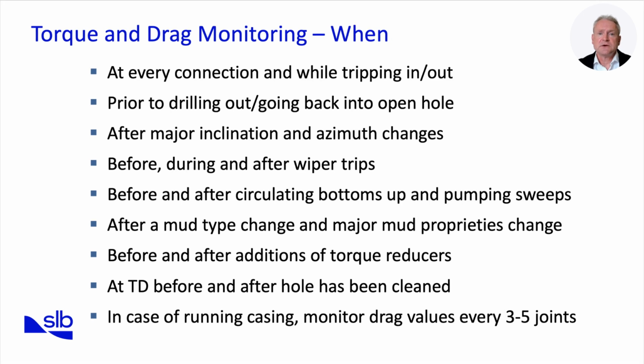When should torque and drag measurements be taken? The key principle is consistency. Data must be captured at critical operational stages so that trends can be identified and compared. Measurements should be recorded at every connection and while tripping in or out of the hole. These are routine moments when the string is already being moved, making them ideal for collecting baseline pickup and slack-off data.